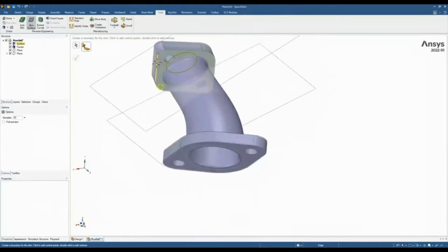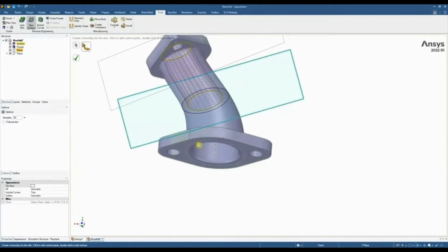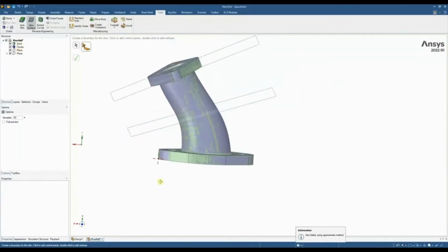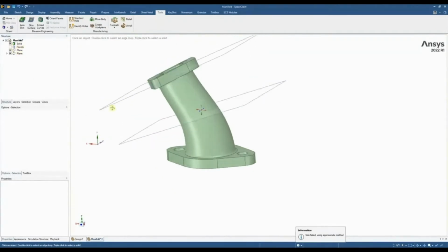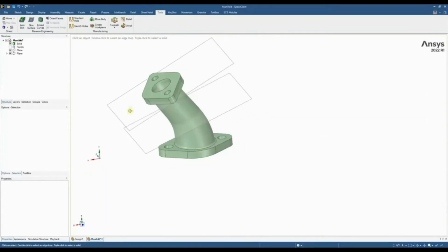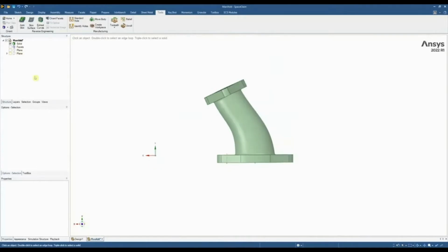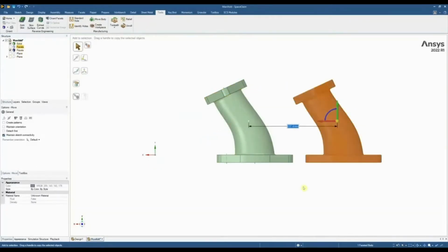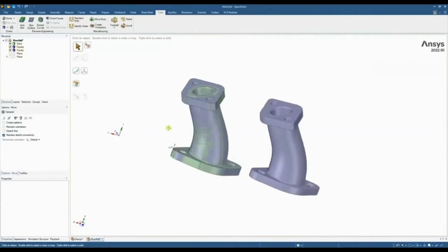And then I'm going to do the same thing now for the inside, hit the tick box, and you can see straight away I've now got a solid model that I can extract and save out as any solid format. So we can see the two side by side. Let's just create a copy of this faceted data, and we can see that nicely overlaying with that.